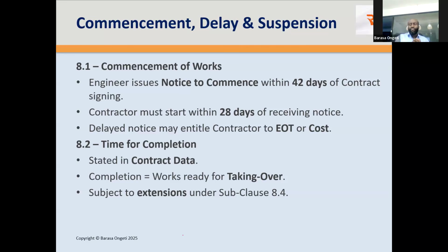Works are ready for taking over when all the tests on completion have passed. So as engineers, you're charged with the duty of making sure that all tests on completion are prescribed within the contract. When you're preparing your specification or your employer's requirements, you state the tests which must be done for works to be considered ready for taking over. If these tests pass, then the contractor has completed the project.